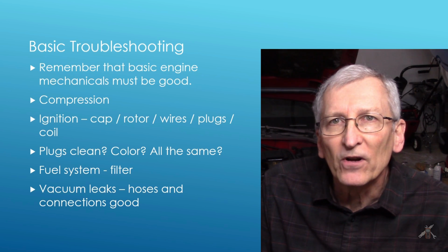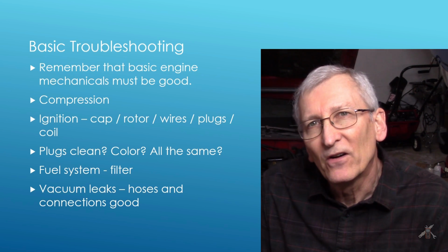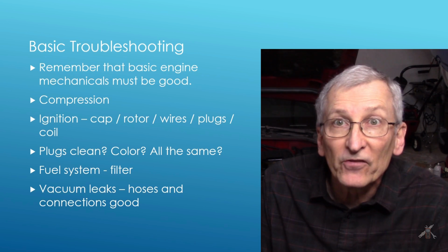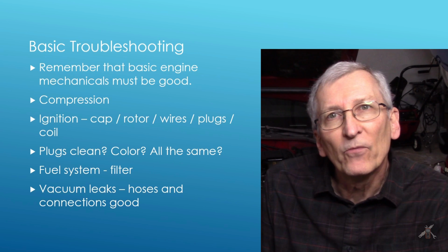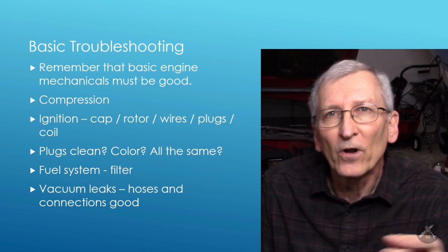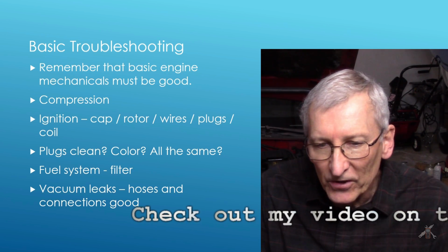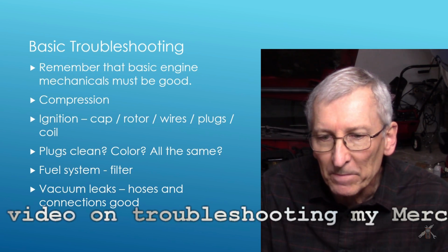How do your spark plugs look? Are they clean? Are they dark? Are they black? Do they have deposits on them? Are all of them the same color, or do you have one of them that's bad? Fuel system, is it in good shape? Is the filter clean? Do you have a good fuel supply?